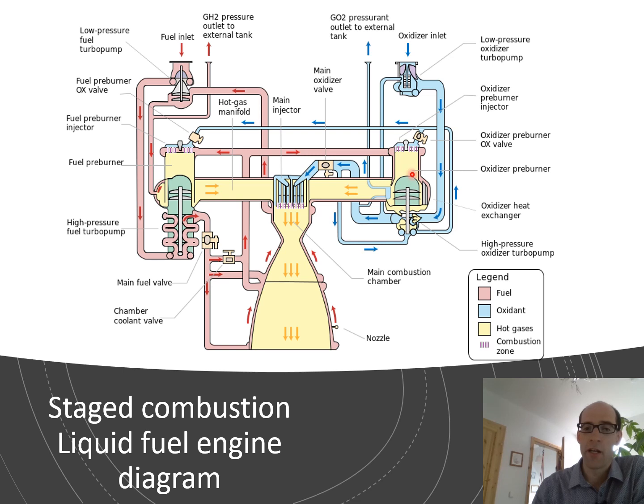The pumps are driven by turbines, similar to aircraft engines actually, and the turbines are supplied with fuel and oxidizer. In this engine here, we have 2 pumps. The pump on the left of the screen is the fuel pump. Fuel is pink. The pump on the right of the screen is the oxidizer pump. Oxygen is blue. The pumps are at the bottom of this assembly here, and the turbines are at the top of the assembly. We also have some low pressure pumps, but I'm not going to mention them. They essentially work in a very similar way to what I'm about to describe.